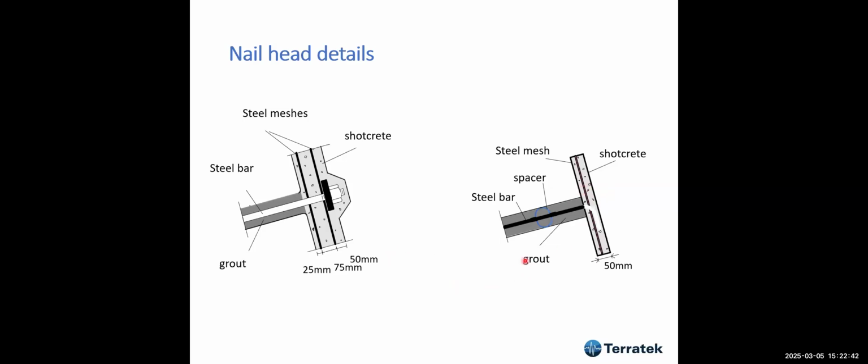In Hong Kong, for instance, I remember they used a minimum of 75 millimeters. But this is for inclined slopes. You should not use the bent bar on a vertical slope. A vertical slope has to be something more elaborate like this, with the plate and the nuts.